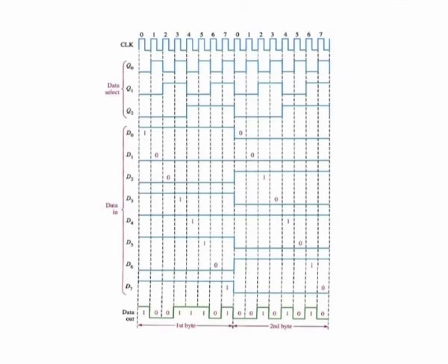The first byte, that is an 8-bit group of parallel data, is applied to the multiplexer inputs. As the counter goes through a binary sequence from 0 to 7, each bit beginning with D0 is sequentially selected and passed through the multiplexer to the output line.